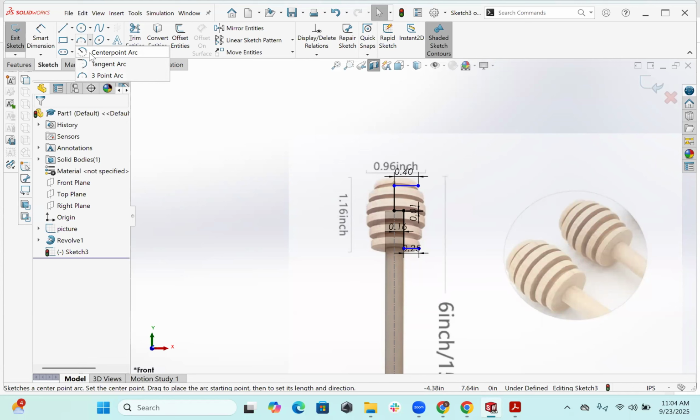So let's revolve this. Feature revolve. Again, first question is what is the center line? We pick it and it creates our piece. Let's check. Okay, remember we are on a section view, so we're only looking at half of this. Okay, now we're gonna go back, create another revolve. I am doing this on a much longer version, so you guys get to see all the features.